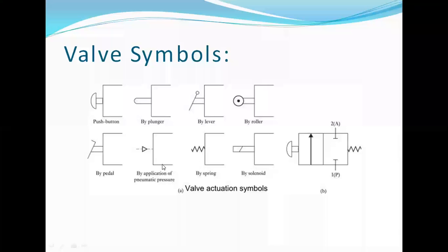And coming to the pneumatic condition, pneumatic in the sense that to actuate these positions, position number one and simultaneously position number two, pressurized air will be utilized. The symbolic representation is this triangular symbol which is supplying. Internally it is in a hollow condition, there are no hatchings. If the internal hatching is fully dark, then the symbolic representation will represent the hydraulic way of strategy. So hydraulic also will be utilized.